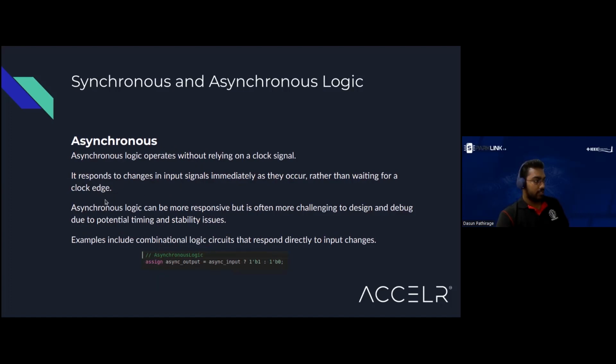Asynchronous logic works faster and is more responsive than synchronous logic, but it's hard to debug. If we have an error, it's very difficult to find the issue. If we have a clock, we can go through the signals and find where the issue is. But if it is asynchronous, it's fast, but it can cause many issues.